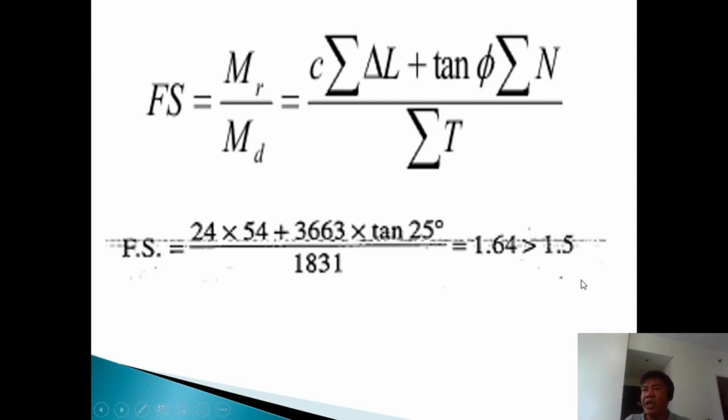Why is it very high? Because these are hydraulic structures, and we are talking here of the pressure of water and the behavior of the soil. In some other cases, we use 1.25 as the limit of the factor of safety, but that is for temporary structures.